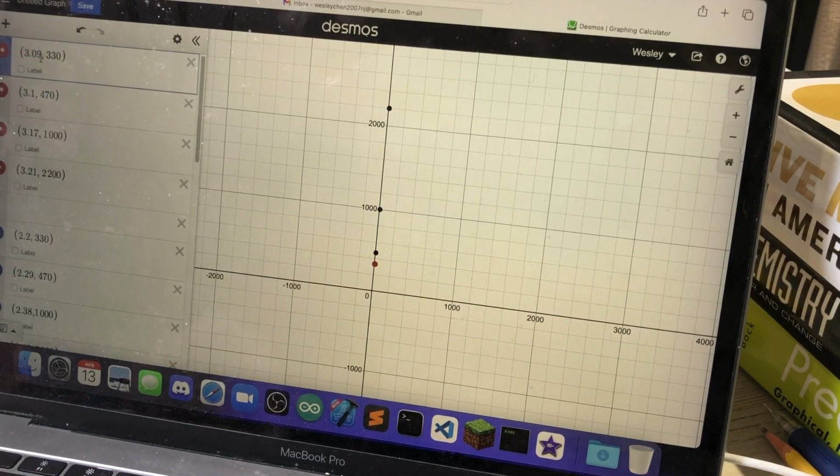So what we would do is just 5 minus everything here. But actually before that, the number here is the resistance. However, we don't care about the resistance. We only want to know the current across the resistor. And recall that the current across the resistor would be the same as the current across the diode because they are in a circuit in series.